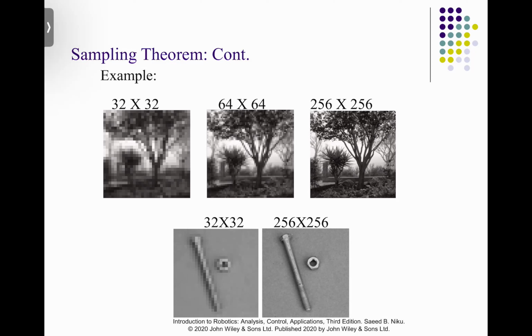Nyquist or sampling theorem. Remember this all the time. Sampling. Basically, what that means is the sampling frequency, F sampling, is greater than 2 times F signal.